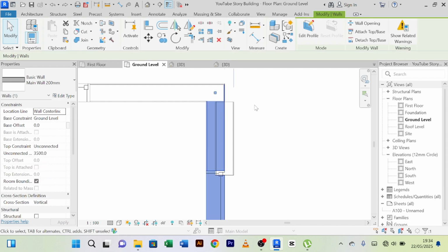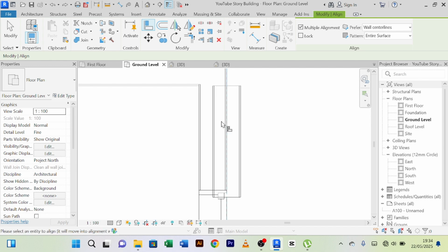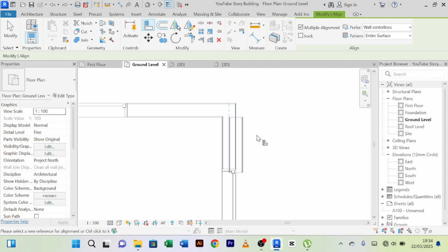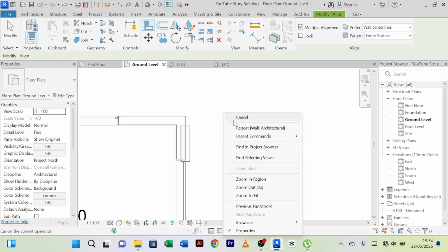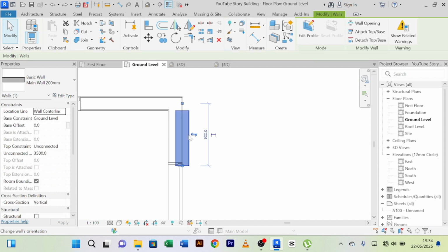I wanted our duct to be at least 1000. So we shall push this window a bit so that the duct can have space. This duct is for collecting water that is coming from rain. So we're going to offset this side. We come to offset after selecting the wall.